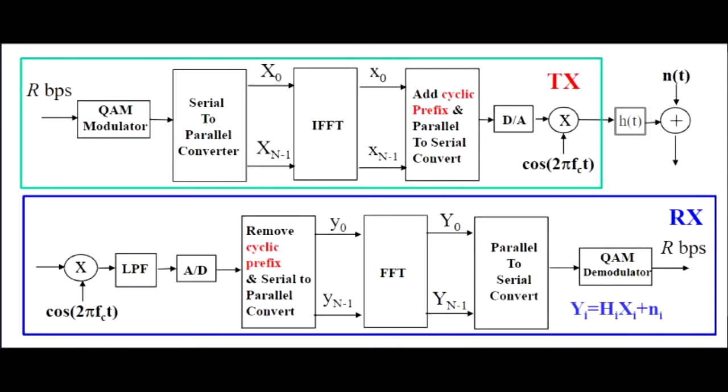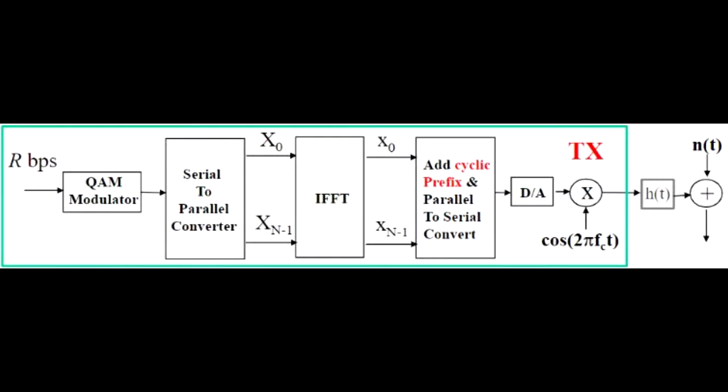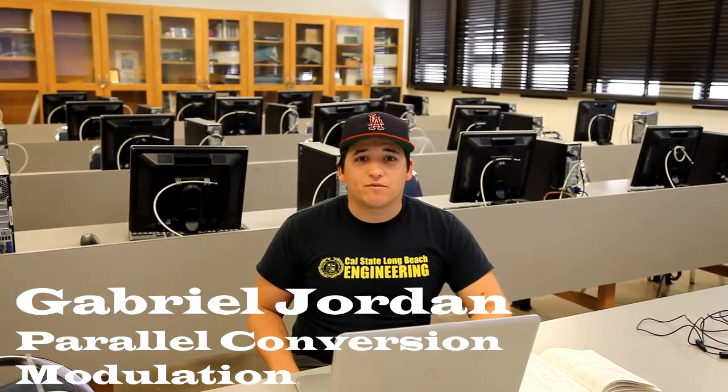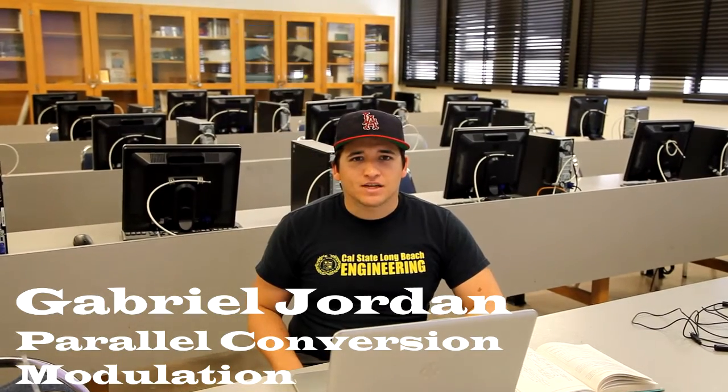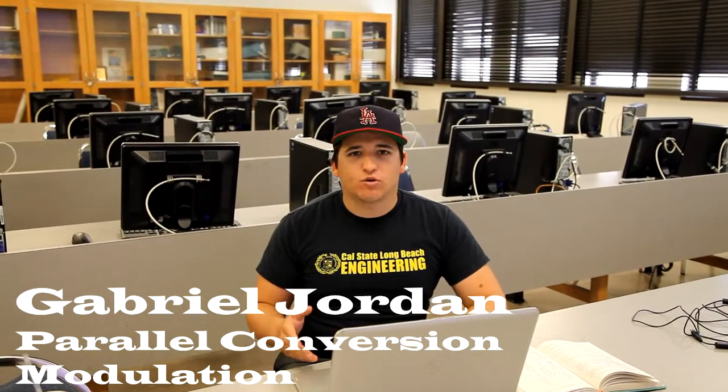Our objective is to recreate the OFDM system in MATLAB based on this block diagram and compare the output data from the input. Each of the group members will explain their assigned parts. We will start with the transmitter. Our input information data will be this image of Sonic the Hedgehog. The image will be processed, transformed into a parallel matrix, and then modulated based on 16 QAM.